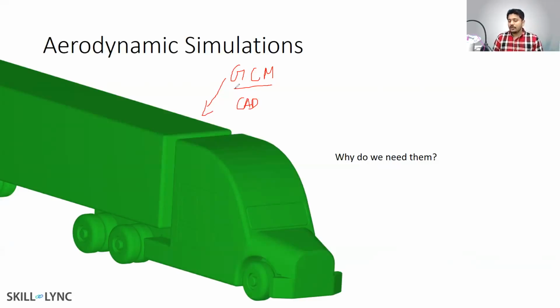The primary purpose is, for example, if you want to reduce drag coefficient and you have a concept, say, if I delay my flow separation point, I can reduce the drag coefficient. You have this theoretical knowledge that you learned from fluid mechanics. You're going to apply that by maybe using a spoiler, or adding a vortex generator on top of the truck so that the separation point is delayed. You can test these strategies quite easily if you just have a good computer, and you don't need a wind tunnel. Or else you need a wind tunnel to do the entire process.